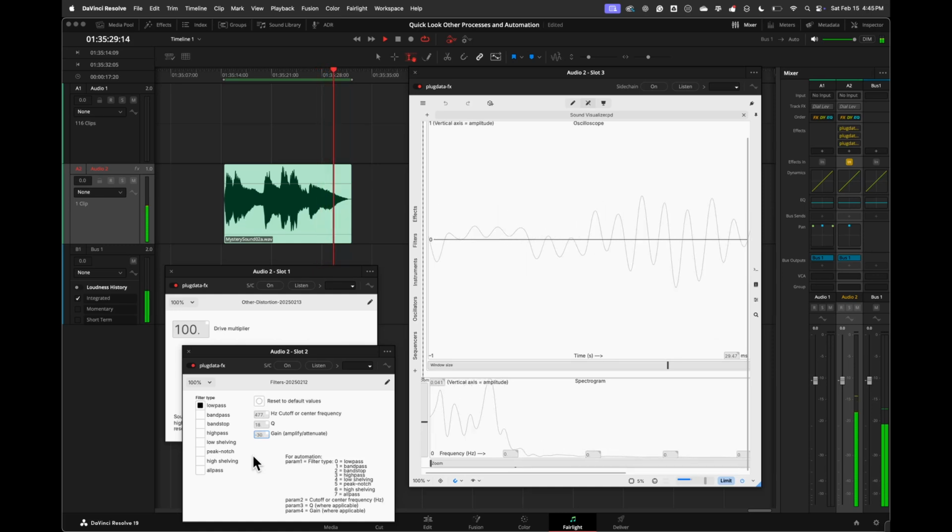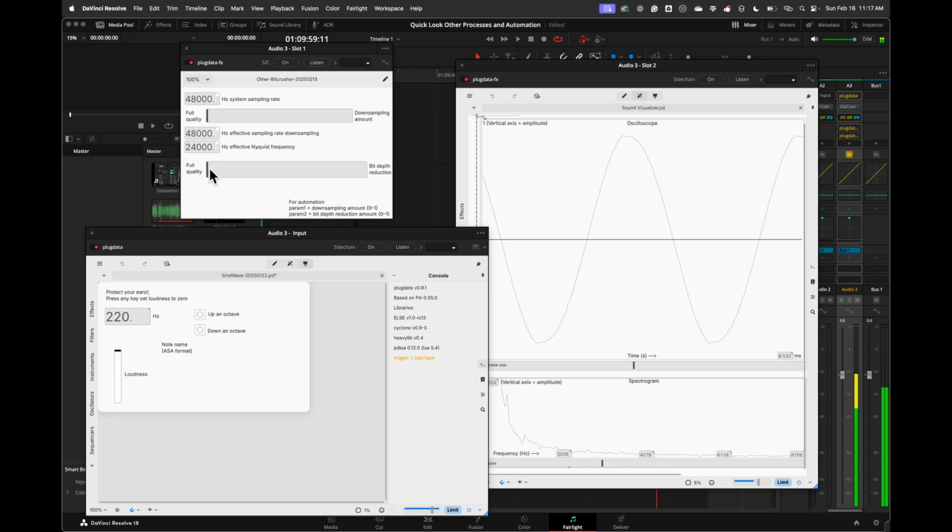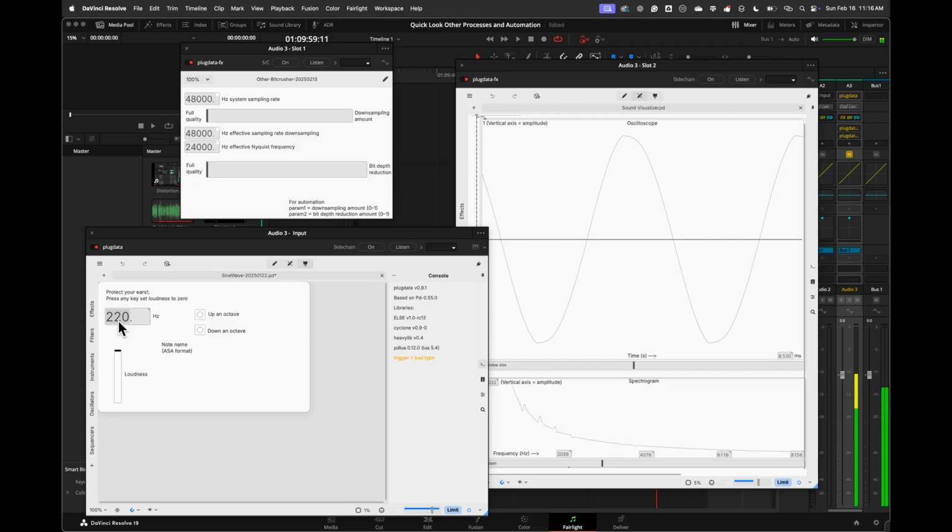Remember earlier in the semester when we talked about the sampling rate and the bit depth and the artifacts we get when we use sampling rate and bit depth values that don't suit the sound? Well, we can actually exploit those creatively. Downsampling refers to pretending that we had a different sample rate, or actually imposing a new lower sample rate on there so we can get the aliasing effect, these high frequencies folded over back into our sound because they're above the Nyquist frequency. The frequency components in our original sound that are more than half of our sampling rate get reproduced incorrectly, and it can make for a nice shimmering effect.